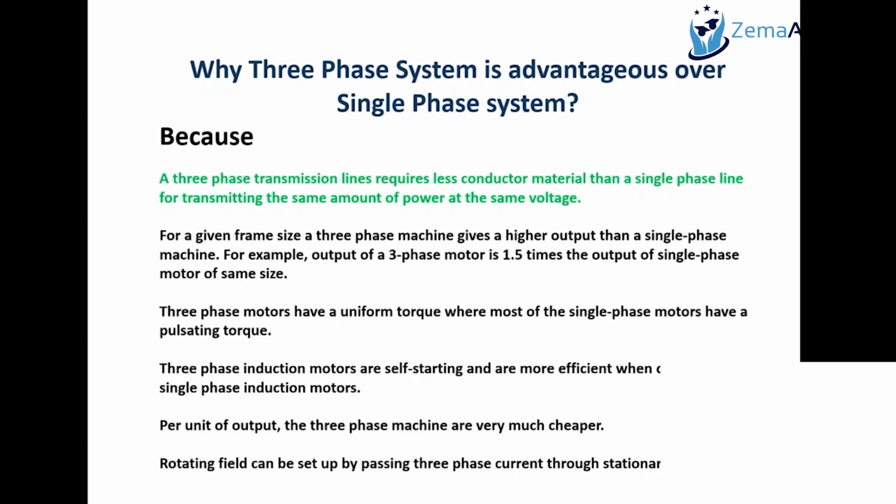So if you want the rotor to rotate, then you need to create rotating magnetomotive forces in the stator. And with three-phase systems, it naturally achieves that, which means that three-phase induction machines or motors are self-starting compared to single-phase motors. Of course, this is not our topic of discussion, but these are the advantages that I can mention about the machines.